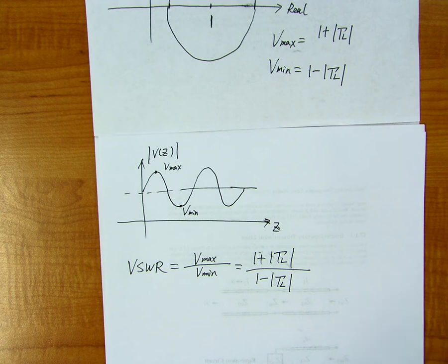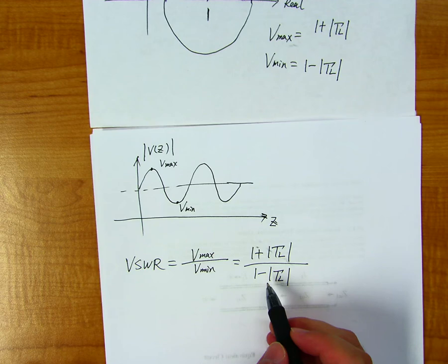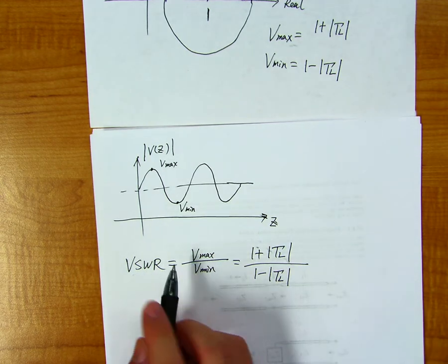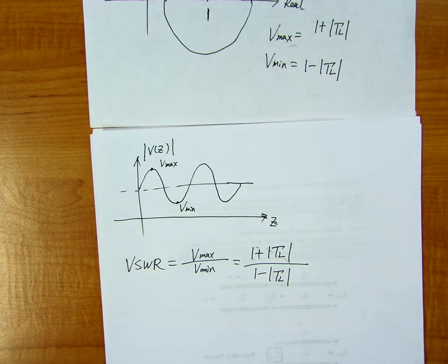But we can actually measure the VSWR, and from the VSWR we can deduce, for example, the reflection coefficient, input impedance, things like that. It's just very easy for us to measure a microwave circuit or microwave system. More detailed knowledge can be found in the lecture note, and you can read it after class. So basically, this is for lecture 16. Does anyone have any questions before we move on?